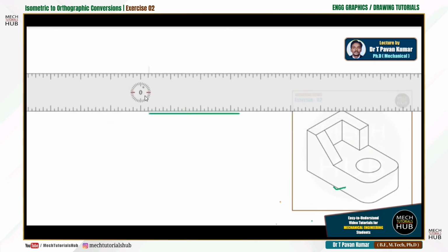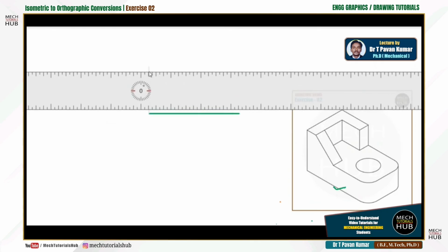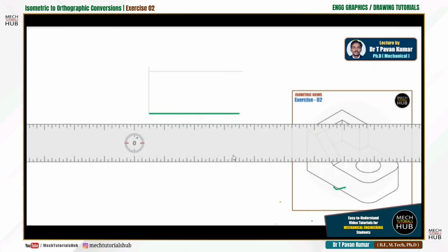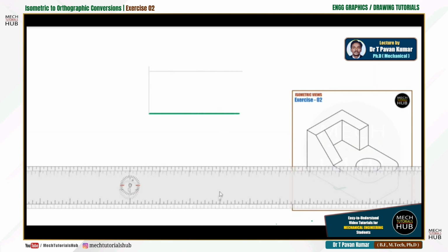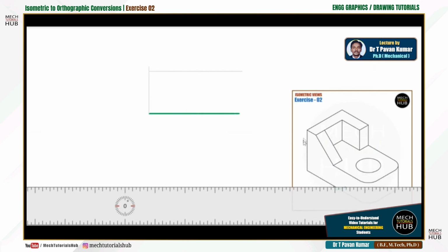Alright, you can take any length, and let me rotate the drafter scale to 0. Again I place it here, drawing one more construction line intersecting here, one horizontal, up to some extent, infinite distance. These two are the construction lines. I'll use the construction lines with a 2H pencil, which will help me further in my sketch. Now this particular intersection is nothing but this corner, and from this corner there is a distance of 10 mm. That 10 mm I'll just make a mark, with green color.